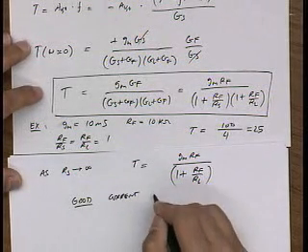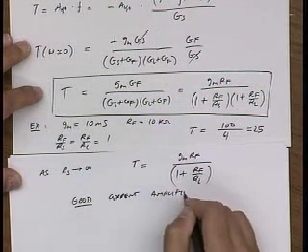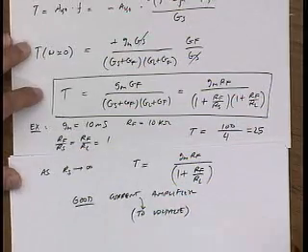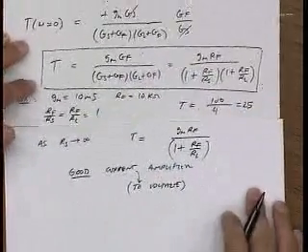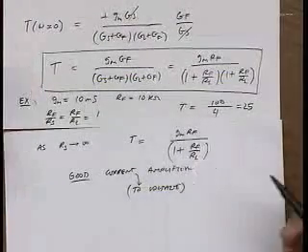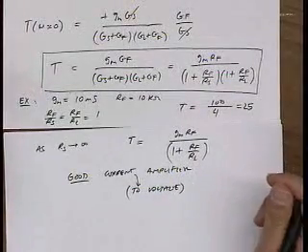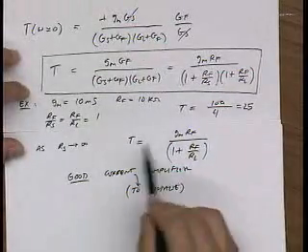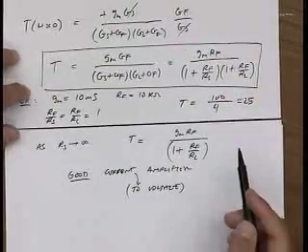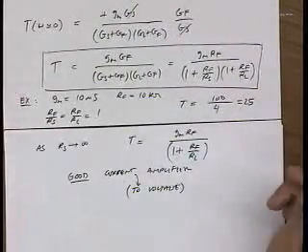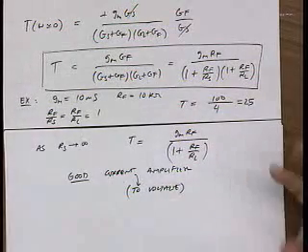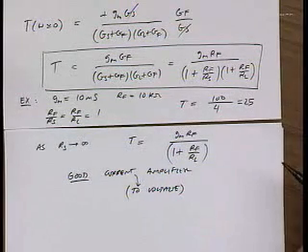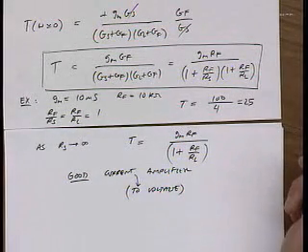So this is a good current amplifier, current to voltage, because the closed loop gain is actually not too strongly dependent on RS. Actually, I should say what we really care about, the loop gain, is independent of RS. So as long as RS is large enough, the loop gain, which determines all the important characteristics such as stability and all that stuff, is independent of RS. So we feel good that we could use this as a current amplifier.